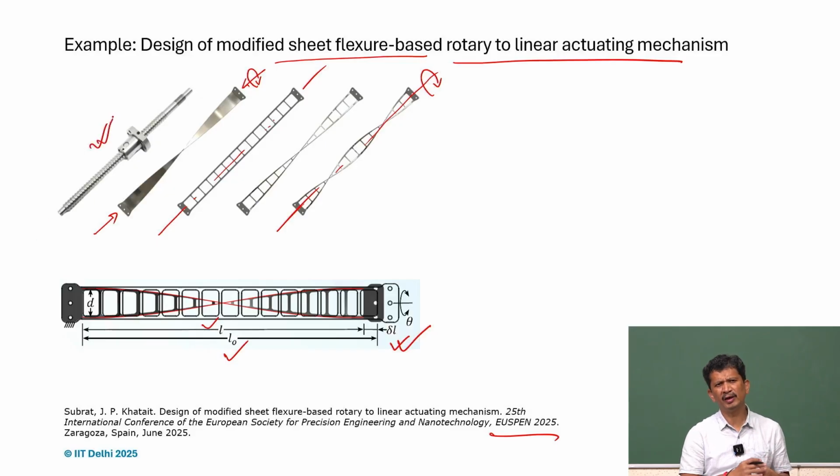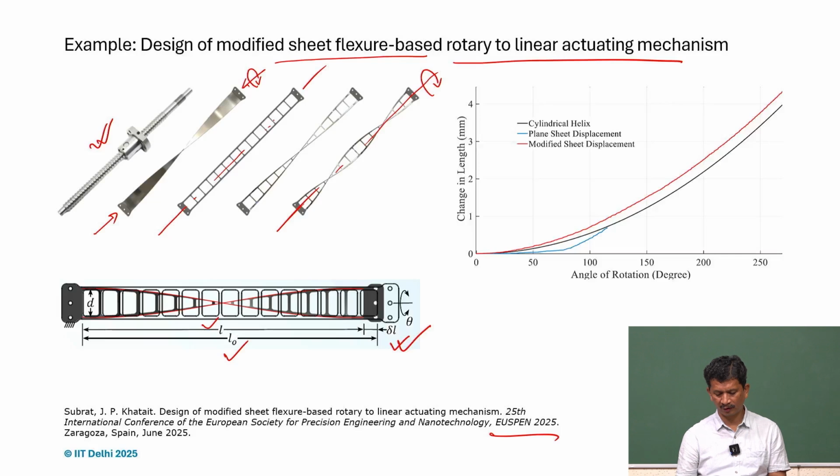It has many parts, but here if we do it this way, and if the requirement is only for a few millimeters, it can be a very good solution. And it's just a thin sheet metal. So again, very effective. Of course, one has to also remember that it has to be in tension. In compression it may not work. So it has to always be in tension, and we have to find a way to keep it in tension.